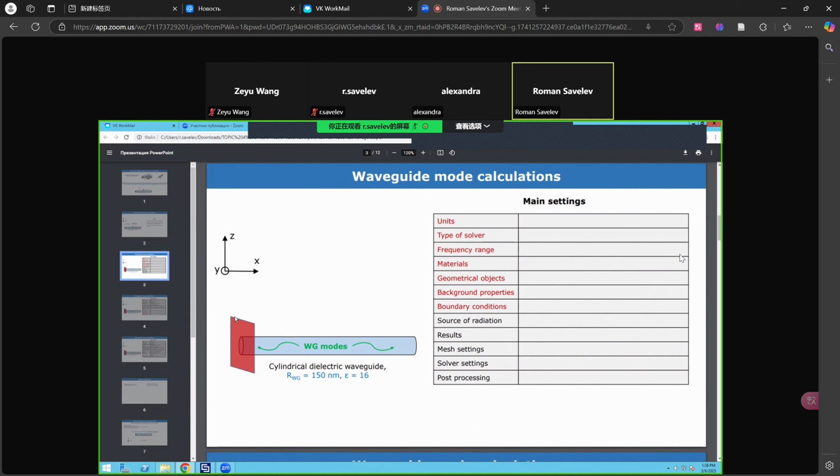The difference is that this particular port, the waveguide port that we will use, has perfect electric conductor boundaries by default. That means we cannot consider radiated modes, leaky modes of the waveguide, only true waveguide modes. We can use material absorption, that's fine. But if the waveguide's mode starts to leak, to radiate outside of the waveguide, we cannot use this approach anymore.